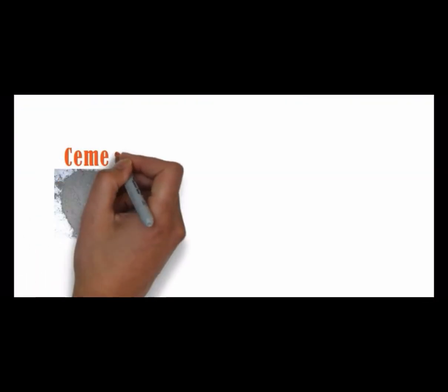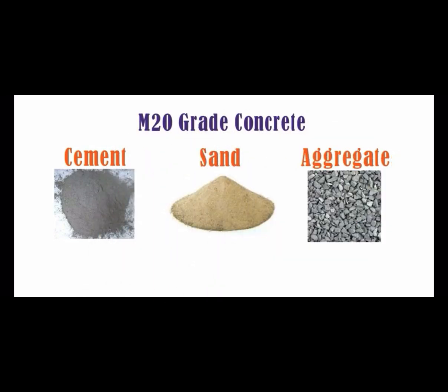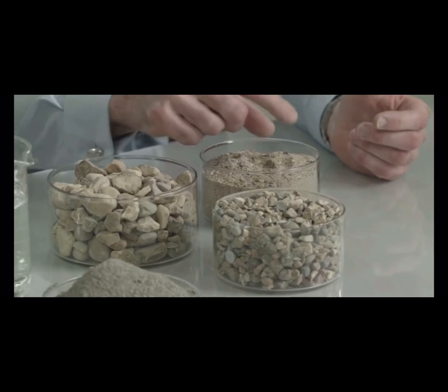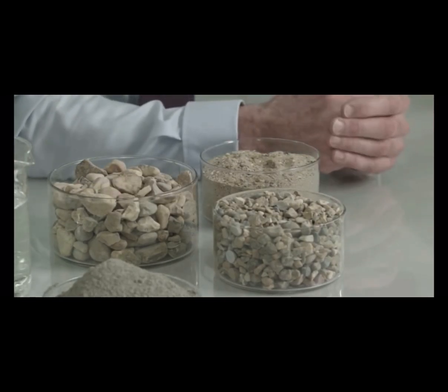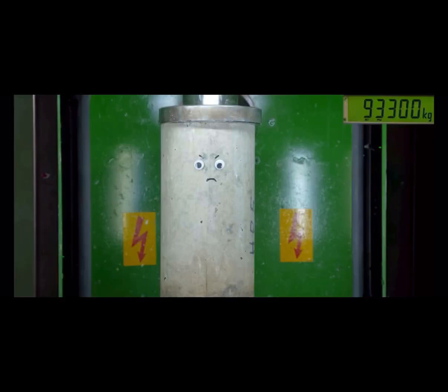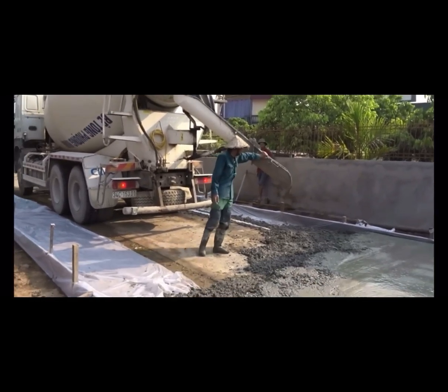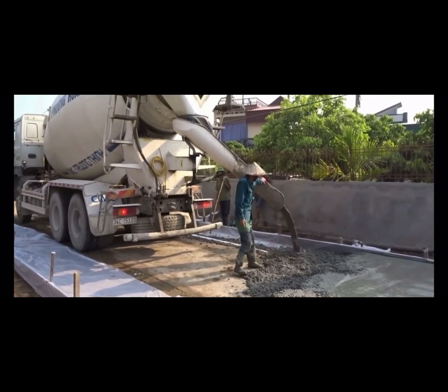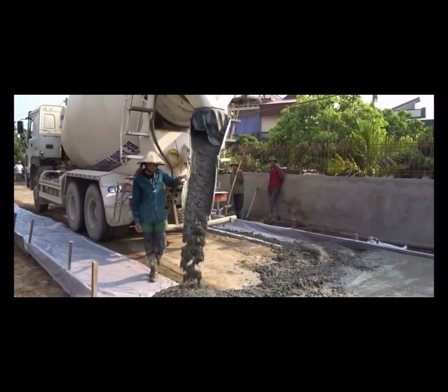Aggregate is the most important component of concrete, comprising up to 75% of concrete by volume. When it comes to composition, aggregate is composed of both gravel and sand. The sand is added so the spaces in between the gravel are completely filled, thereby giving the concrete stronger bonding and consistency. A well-graded aggregate, which is a balanced mixture of coarse and fine particles, reduces the requirement of cement, thereby making the whole process much more cost-effective.